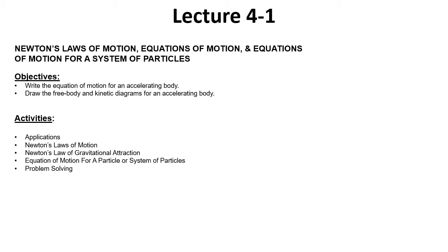So we'll go through how to do these in a couple of example problems, take a look at how we go from a free body diagram into our equations of motion, how we can use our summation of forces, summation of moments, and use all that information to develop these equations of motion.